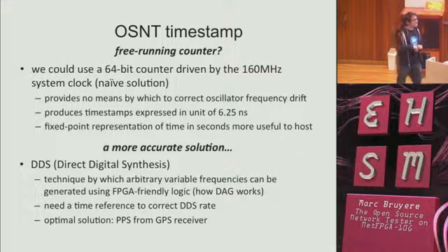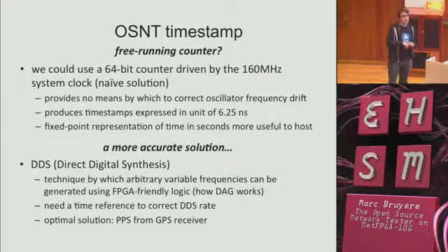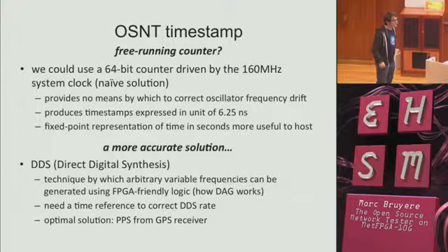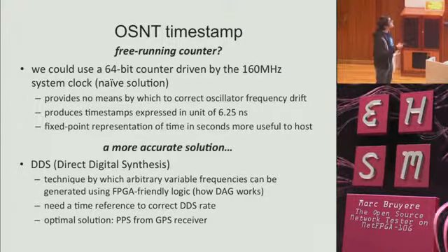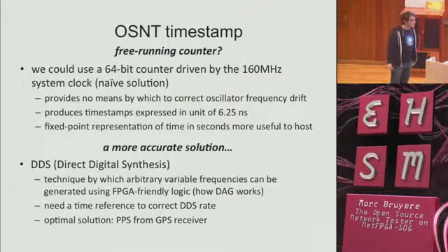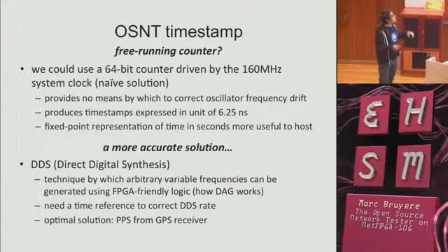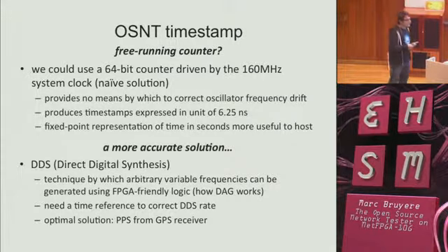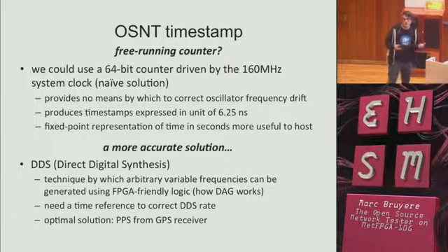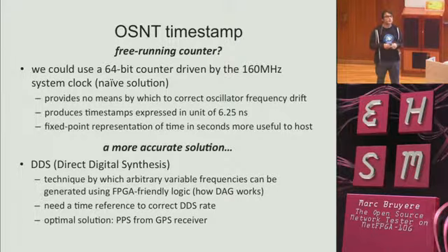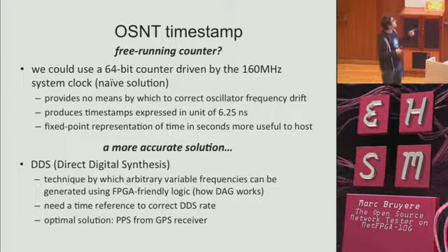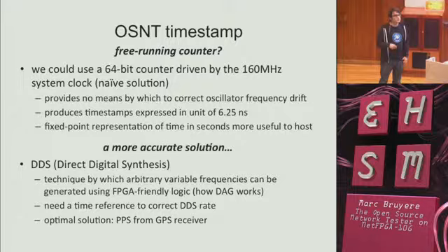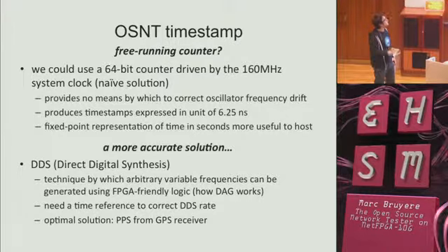Then we had to decide the way we were going to do the timestamping. It was very important, and that's one of the reasons I joined that project as part of my PhD, to measure latency in an OpenFlow environment. There are two ways to think of the implementation. Either you use a free-running counter directly driven by the clock itself, but the clock of a board like this will drift when you need nanosecond precision.